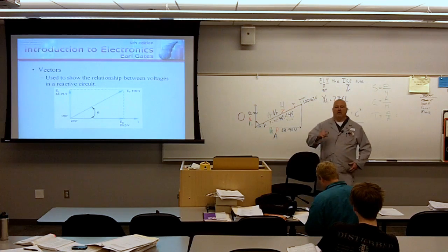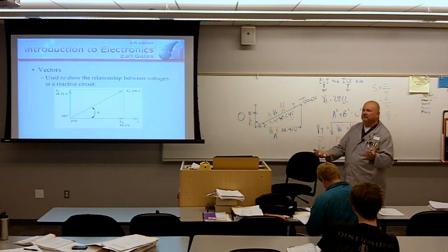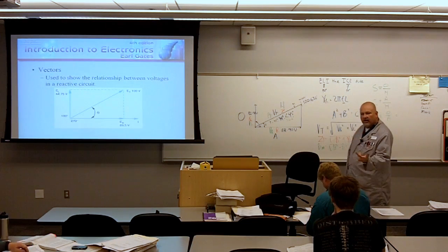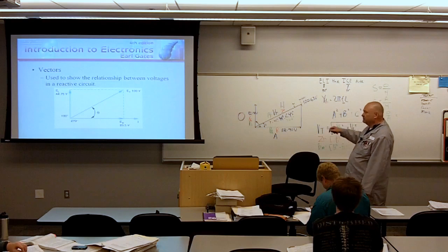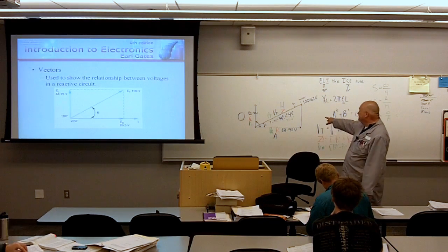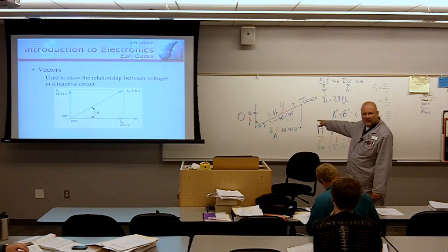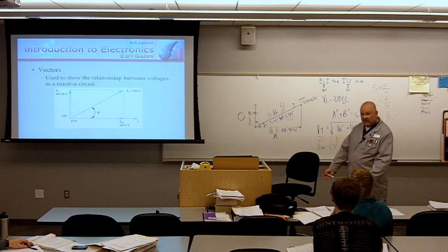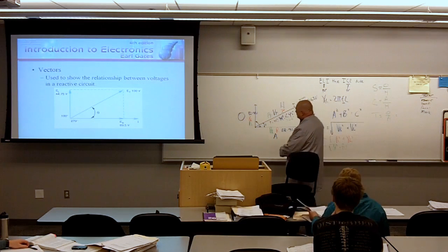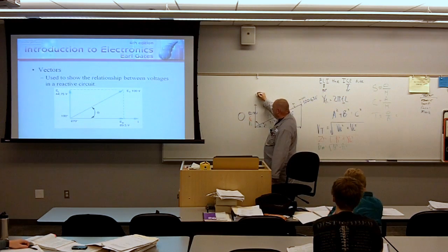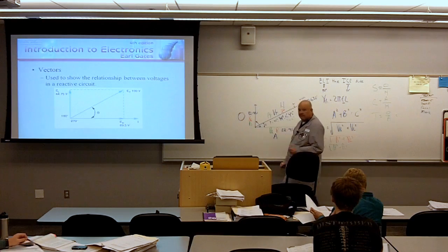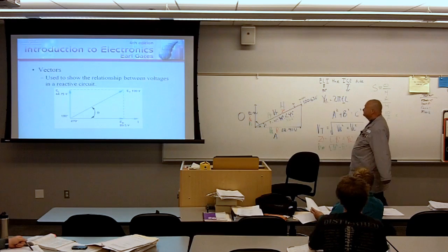By this illustration, there's so much that I could tell. By just looking at this, I could tell this is a series RL circuit. I could tell that this is predominantly a resistive circuit, but it has some reactive components. By seeing that angle theta is 26.6 degrees, that tells me that it's predominantly resistive and not reactive. If I wanted to make this more reactive, if I wanted to increase the length of my opposite side, how could I do it?